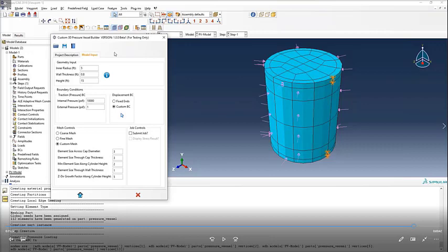Is it possible to automate models with nonlinear compression only springs and the like? You can. I think I've done one similar example before. Some of the Abaqus functionalities are not available through the GUI. If you get into those, the way we have modeled it before is to modify a text file.